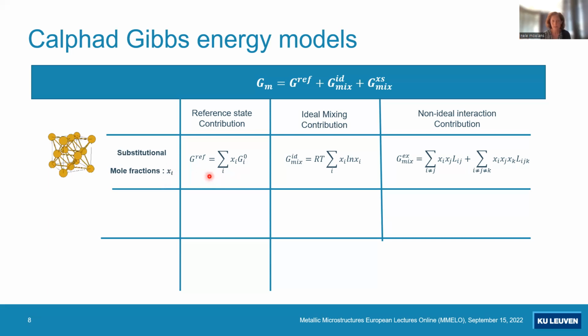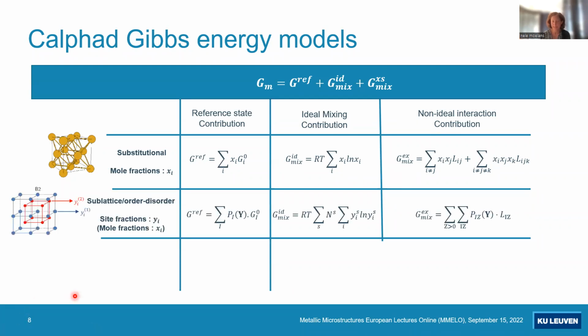So in fact, in that case, if we have this reference energy and if we have these interaction coefficients, we could just implement all these expressions in our phase field model. We can also do that for a quaternary alloy, and in fact it works, and it works well. Of course, if the database is encrypted and we don't have the coefficients, then we have to find another way. But there are also other more complicated models.